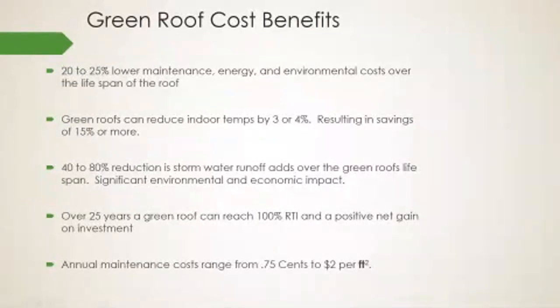Okay, so the kind of rough estimate, over 25 years, a green roof can reach 100% return on investment, and a lot of times even go into the positive net gain side of things on that investment. So over the long term, they're a positive net gain investment. And annual maintenance costs, just in a general estimate, is somewhere between 75 cents to $2 per square foot of green roof, depending on, again, the system, what's there, if it's extensive, intensive, somewhere in that range.